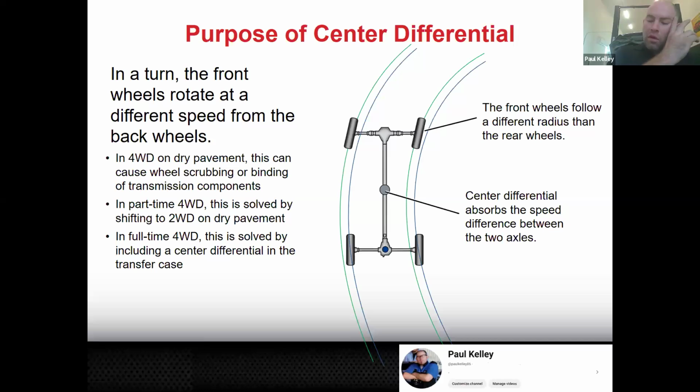So this is the overview because we have the beautiful arcs right here showing the different wheel paths, the rolling path of the tire. When we deal with all-wheel drive, we're very concerned about tire diameter and ultimately circumference, meaning the size of it in a circle, the outside diameter, because that equals RPM. And we can have a little speed difference left to right. Those differentials are made for that. Most of them are open diffs anyway. But the center ones, they don't really like a whole lot of that. And that's why we're so worried about it on your all-wheel drives.